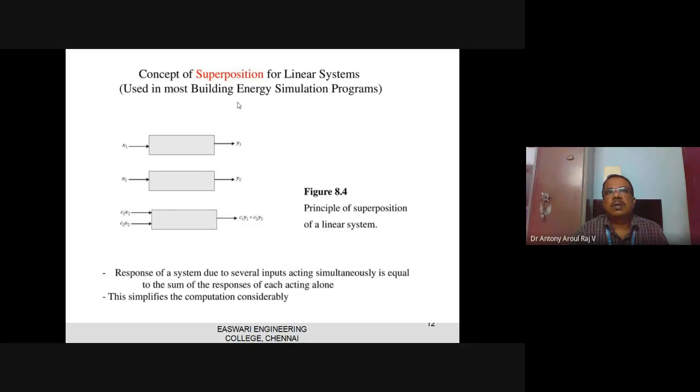Because if I do the same calculation during the month of June, the exposure for Chennai will be in the north, because it will be the June solstice. So the exposure will be in the morning east and north. Now I think you have to understand that solar temperature is typical for each surface, so you have to do the calculation for each surface separately.